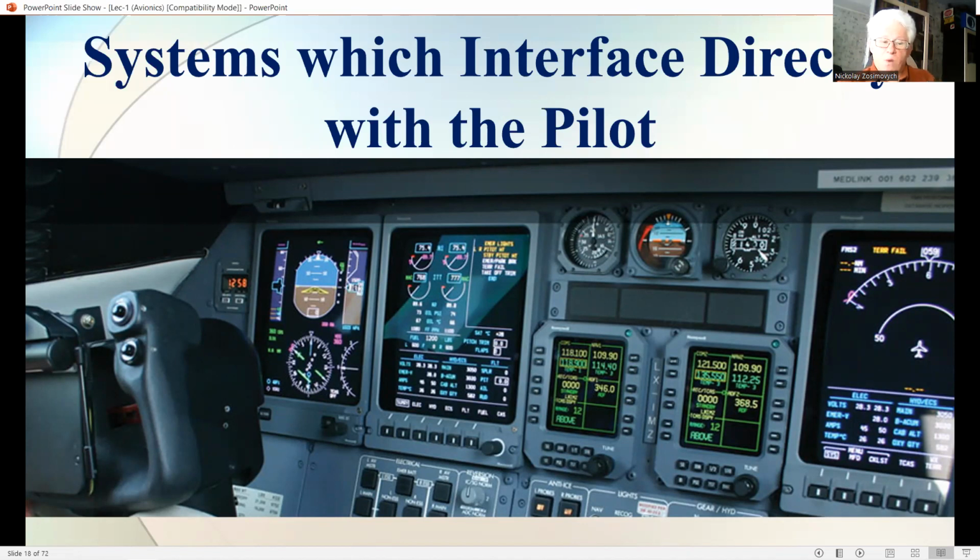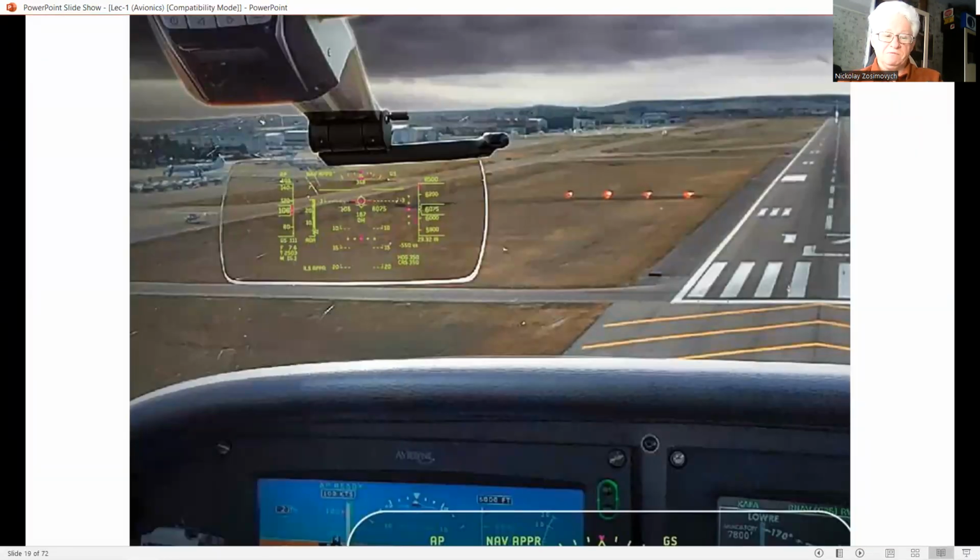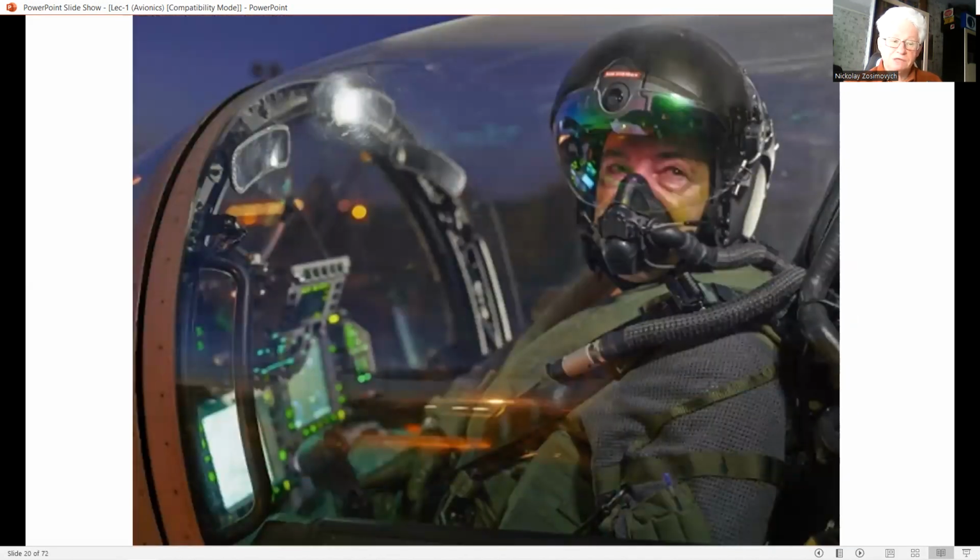The display system provides a visual interface between the pilot and the aircraft systems and comprises head-up displays, HUDs, helmet-mounted displays, HMDs, and head-down displays, HDDs. Most combat aircraft are now equipped with HUD. A small but growing number of civil aircraft have HUD installed. The HMD is also an essential system in modern combat aircraft and helicopters.